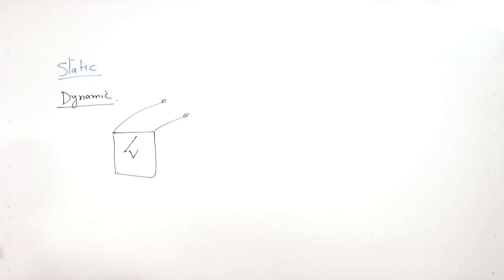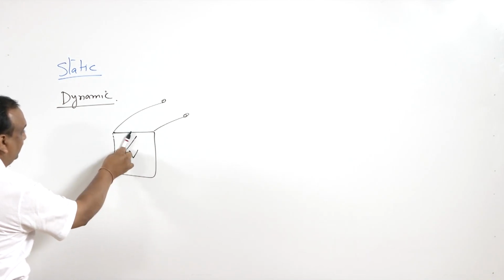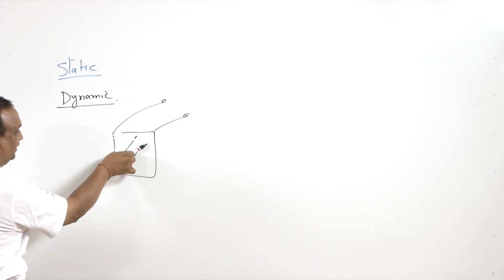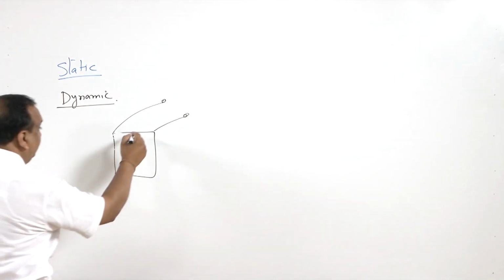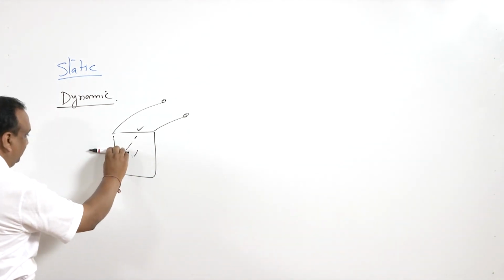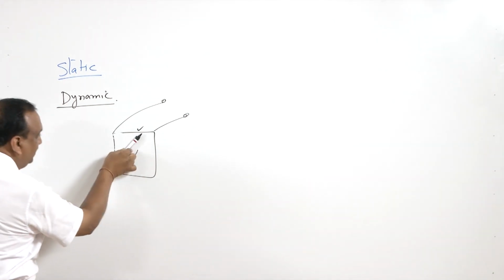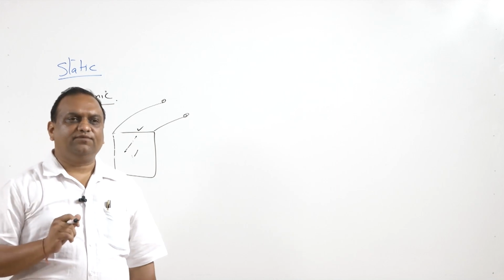Second type of response is, this is a sluggish response. Second type of response is, the needle will move and it will overshoot the input and it will start oscillating. And after a certain time it will be damped and it will indicate a certain value. Right? So it takes certain time to stabilize. So that is also not very good. Very good dynamic response of the instrument. Third type of response you must have noticed that the moment you give input, there is no output, there is a time lag, and all of a sudden there is a movement in the needle. So you can have variety of outputs, variety of responses of the system for a given input.